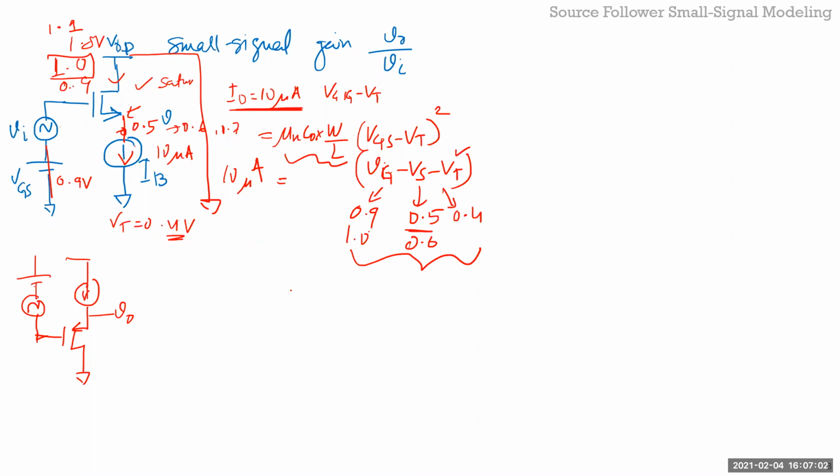So if your impedance is not matching, you did an amplifier, but you're driving a huge load, then you buffer it by a circuit like this, because your input impedance looking in over here looks just like a cap, but the impedance looking here, you'll see when you do the small signal analysis, it'll look like 1 over gm. And if you bias this with sufficiently high current, then that impedance can be lower.